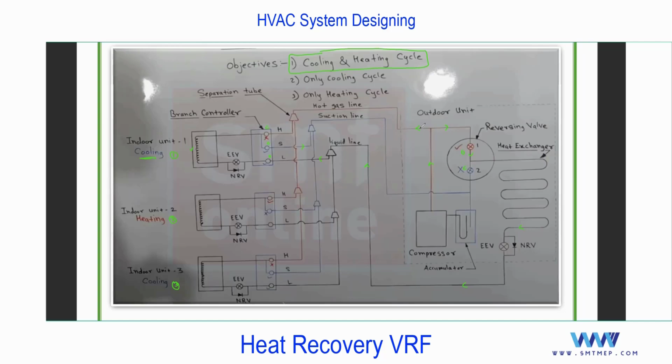So the hot refrigerant here, this valve will open for this unit because suppose in this room they call for heating. So this valve will open and this is going to be closed and this will open. So the hot refrigerant will enter and this will become what? Condenser, right? And the hot refrigerant, 1 minute. Condenser, it will reject, it will lose the heat.